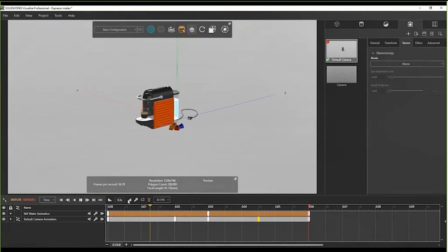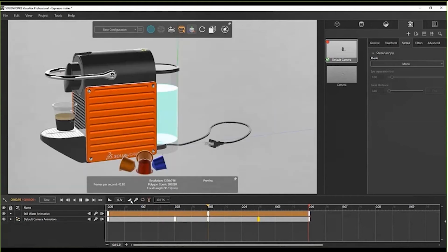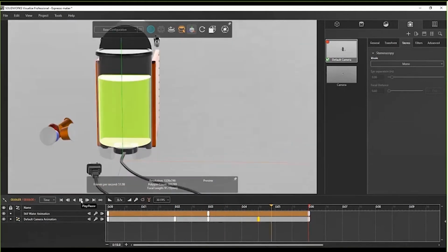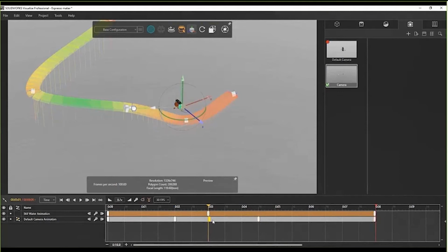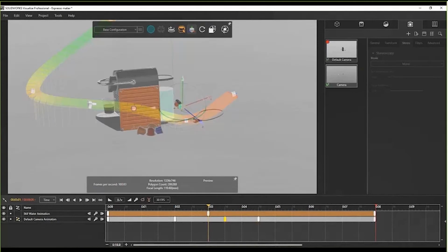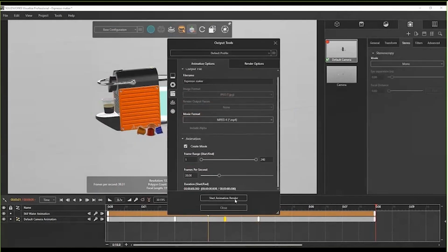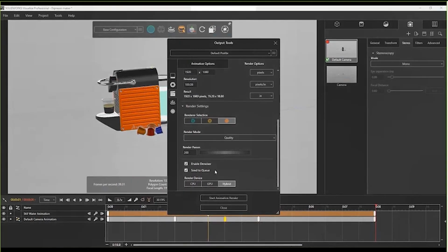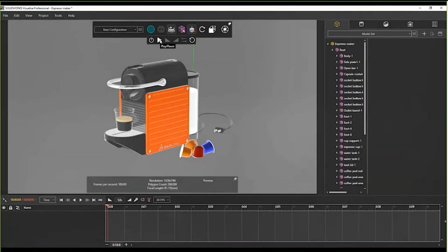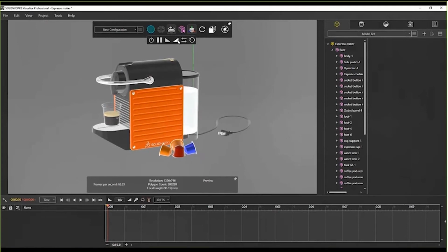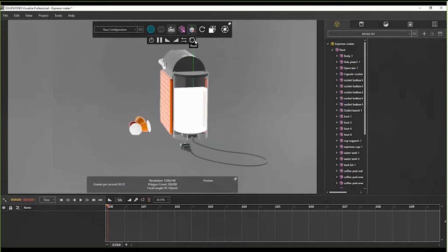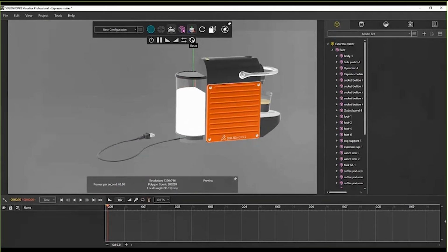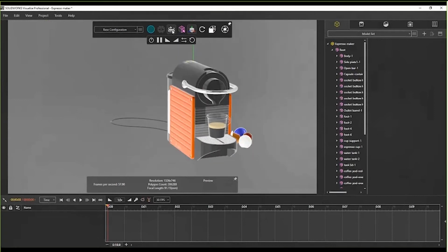So now if we run through this, instead of it going into hyperdrive and straight through my part, it's doing that clean swivel around to the exact position that I wanted, right? And with a little bit more fine tuning, we could get it exactly where we want. You can start to fade things in and out a little bit cleaner. But once this thing's good and ready to go, I'll check my settings and kick it off to the render queue. Now, for things that are very standardized, like a 360 spin, you've got the little icon for what's called a turntable at the top, and you can have this thing set on that 360-degree spin and have it repeat over and over again if you want to, right?